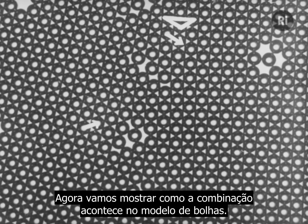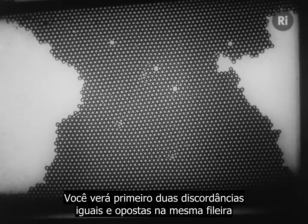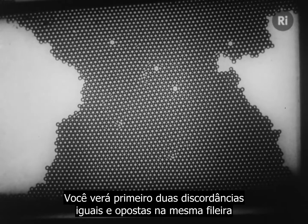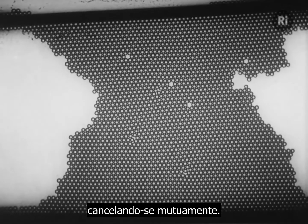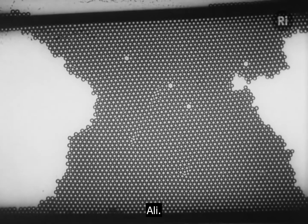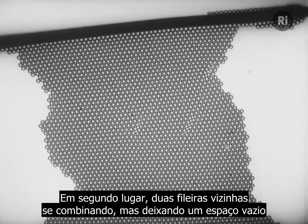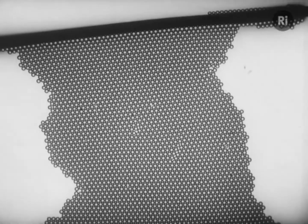The combinations will now be shown taking place in the bubble model. You will see, first, two equal and opposite dislocations in the same row cancelling each other. There. Secondly, two in neighbouring rows combining but leaving a vacancy. Thirdly, dislocations leaving a complex of vacancies.